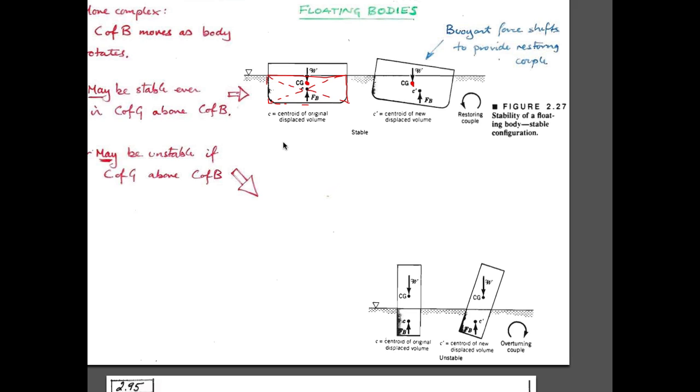But if it rolls for some reason, because there are heavy seas and it has inertia from the last wave that went past, all of a sudden this isn't a rectangle anymore. And actually, probably not a bad estimate of where the center of gravity would be. Well, the centroid of this is actually, if you can draw a line through here, and if you can draw a line through here, well, no, it's not quite the case.